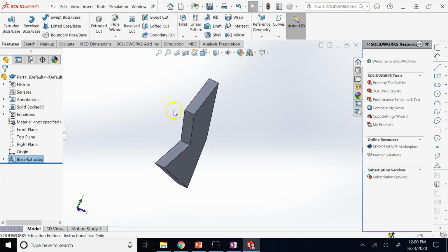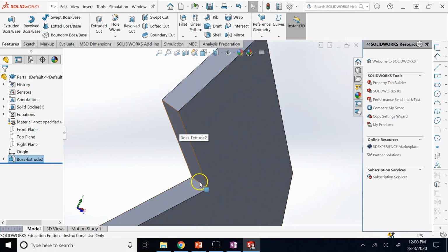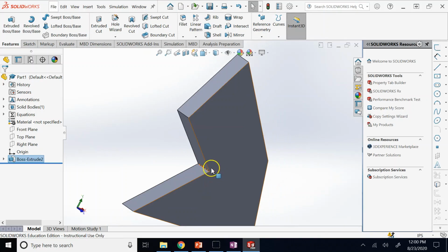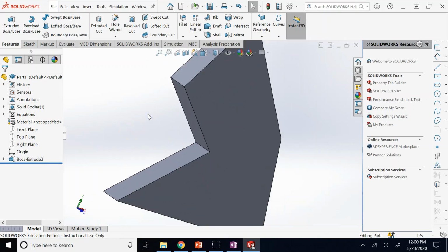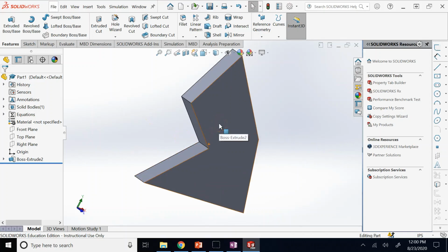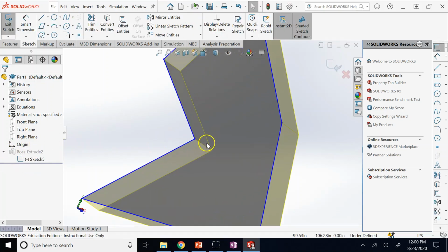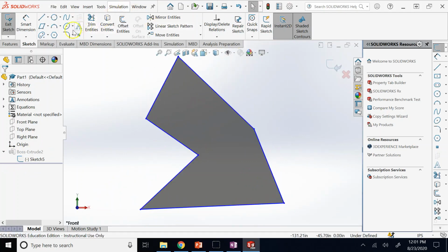So if you put this part under pressure or under loads, at this point the part is going to be weak, and it makes the part fail quite easier and under a smaller load compared to something that has this part filleted out. So this part with the sharp internal edge will fail far easier than if you just applied a fillet here, right?